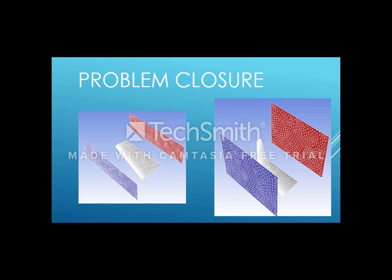Looking at the images shown, the blue faces were defined as the inlets. The red faces were defined as the outlet, and the airfoil was defined as a wall. The 4 other sides of the rectangular domain not shown were also set to walls. The inlets were set as a velocity inlet and initialized to have a magnitude of 50 meters per second.